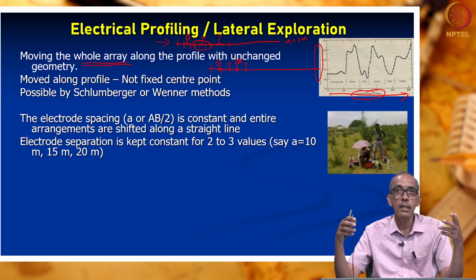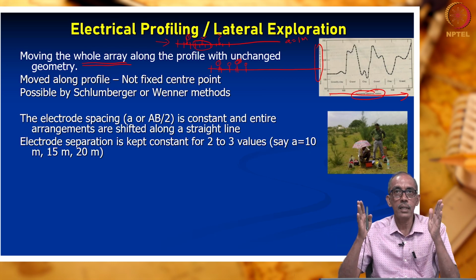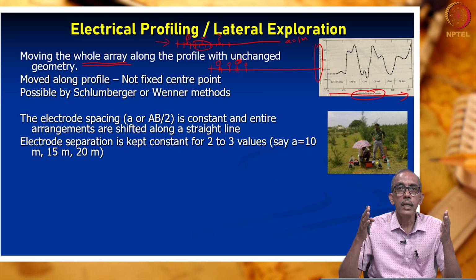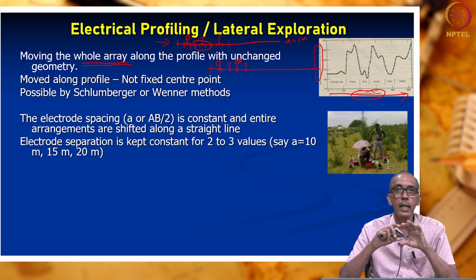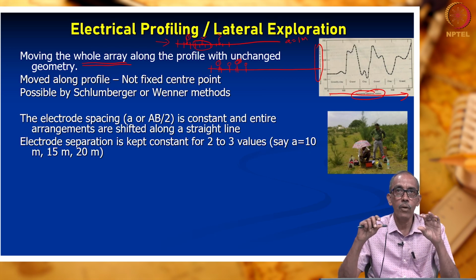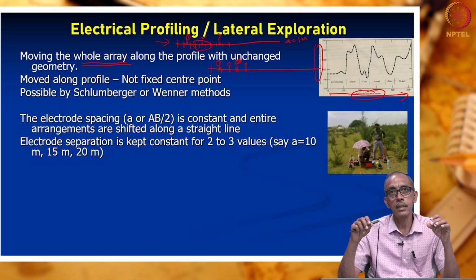The pipeline will be buried by cut and cover method. So, you need to understand what will be the cost of carrying out the operation, the earth excavation, and burial of pipes, whether any support is necessary for the excavated area, whether any reinforcement has to be done, any barrier walls or barrier sheets have to be provided. So, in that case, you have already decided the pipeline has to be 5 meters below the ground level. So, our depth of investigation needs to go up to 5 meters.